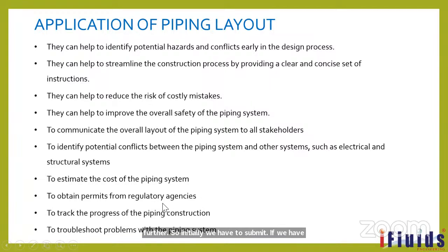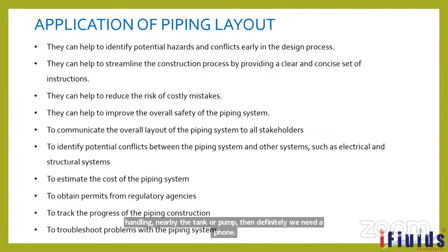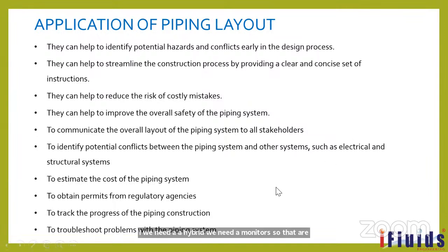If at the last minute, after you construct everything, they don't give approval, it will be a huge loss. Because if you are handling any flammable substance near the tank or pump, then definitely we need foam, we need a hydrant, we need monitors. All that beforehand you can get approved by the local government bodies.